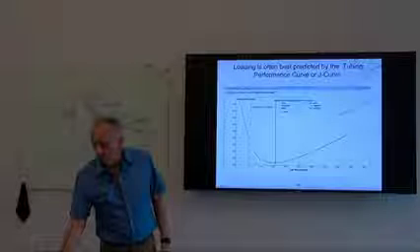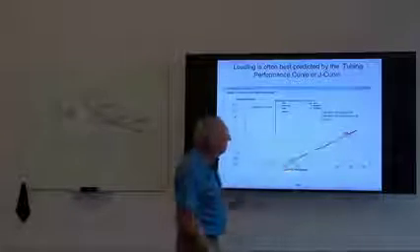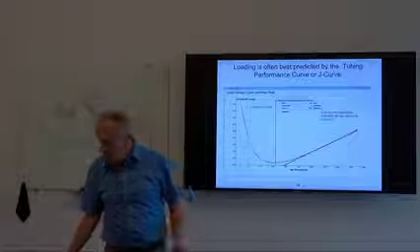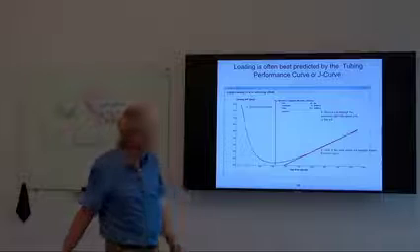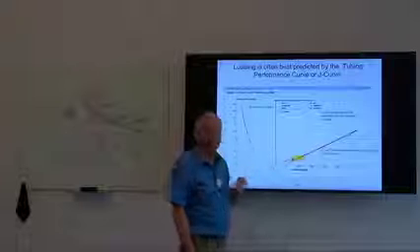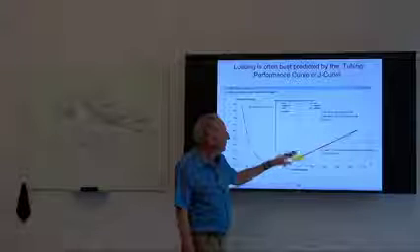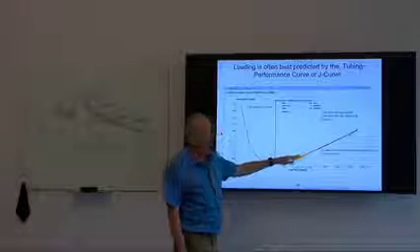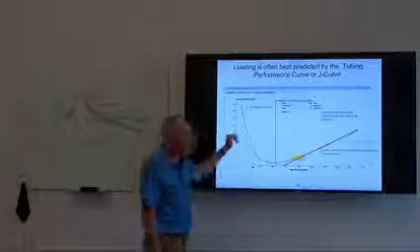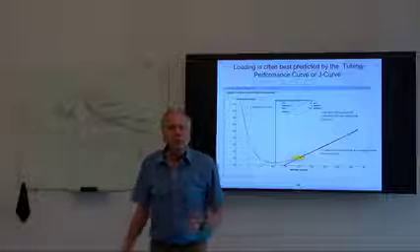So today, what we typically do is we look at this friction-dominated side of the curve, and we draw a straight line and say, okay, that is our 100% friction line. Then we look at this area here, where the curve breaks away from the tangent. The reason the curve breaks away from the tangent is we are now seeing a transition to hydrostatic contribution to this bottom hole pressure. Even though the pressure is not going up yet, it's bending this line because liquid is starting to accumulate.